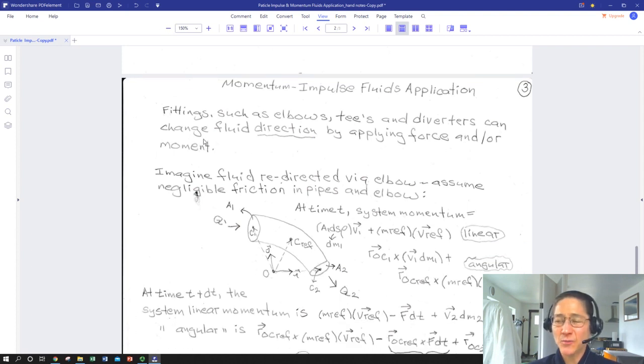So once again, important thing, once we've got a force being exerted by that reference volume due to momentum change and impulse, then we've effectively got a force being applied to our pipe, our elbow, our container, whatever, and we need another force being exerted by something else to keep it from accelerating. We don't like our piping system to start accelerating. That can cause all kinds of problems. Worse when it's filled with flammables.